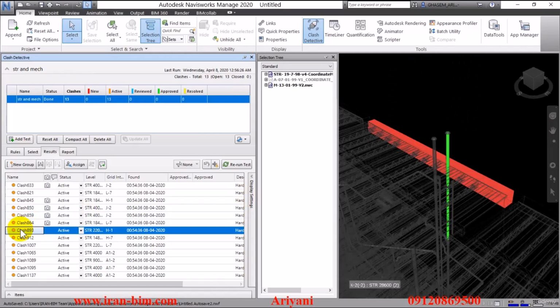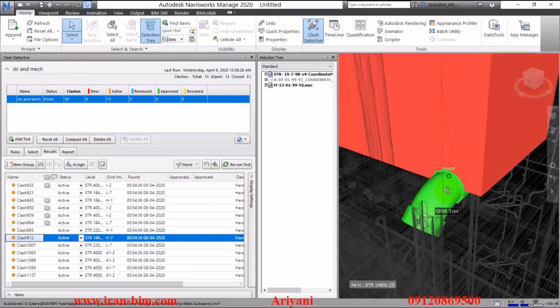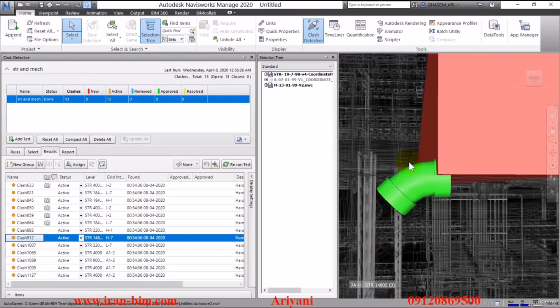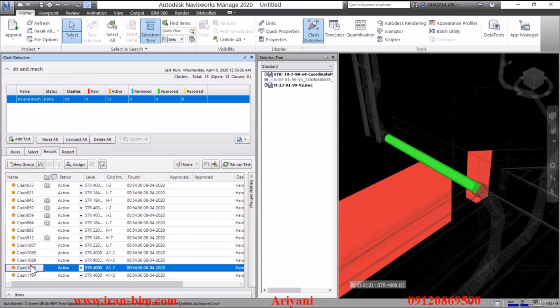And as you can see, almost all of the clashes are very minor, and this one as well. And overall, 13 clashes only is an extremely good number for us. But if you actually remember, we had a lot of clashes in the architecture file. Most of these about the sewage pipes in the underground on the first and second floors.